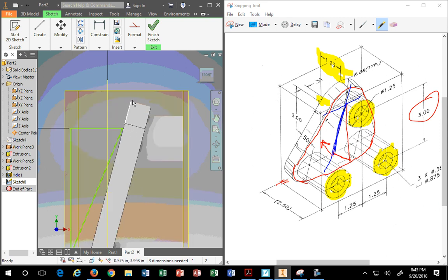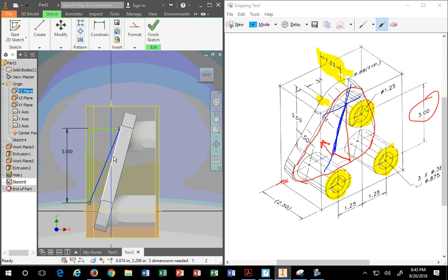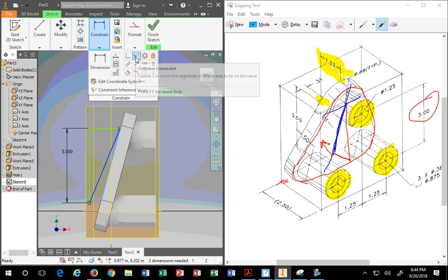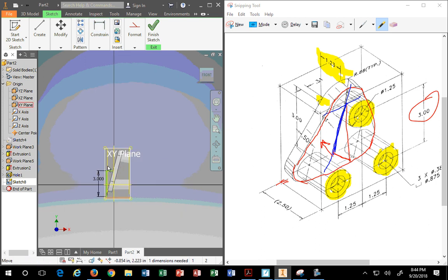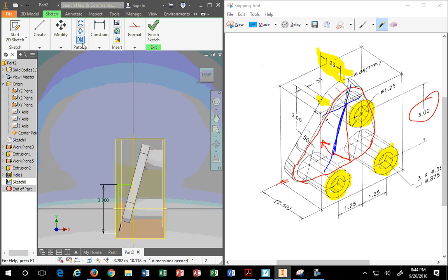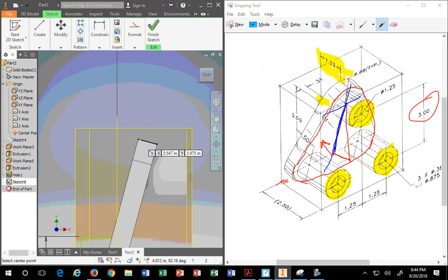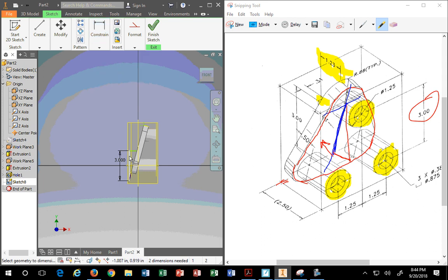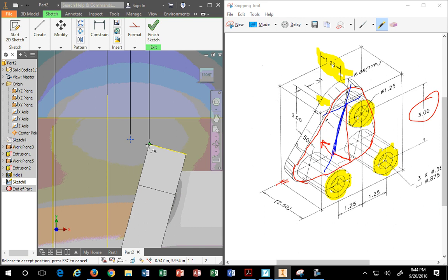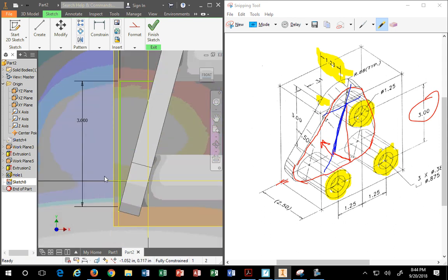It's probably from here. So now if I try to attach it to this, not that, attach this, hold my control key down to this, and use collinear, it will attach. It'll move on the surface. It'll slide up and down the surface. Now if I assign that dimension, before I can do it though, I have to put in a point at this intersection. This point has to be attached there. Now if I go ahead and dimension it from here to that point, put in 1.23, the point moved off again. Sorry, let me drag this over. And this slides up to wherever it goes.